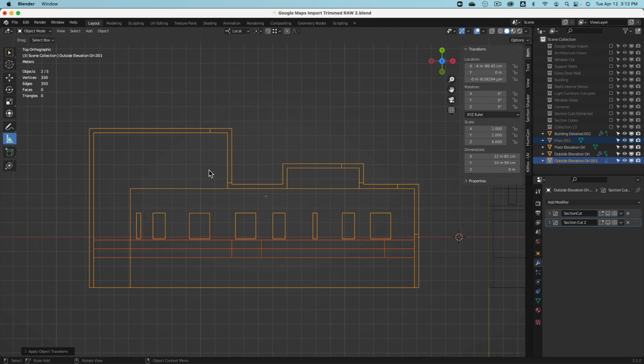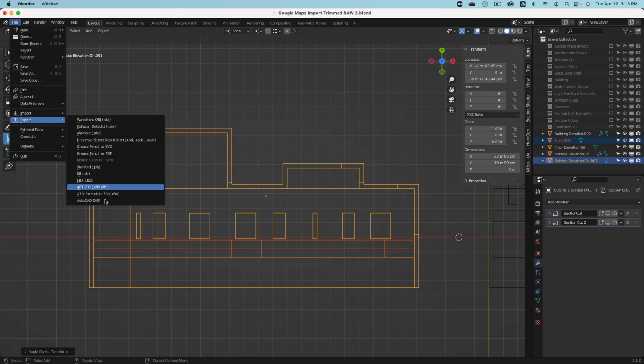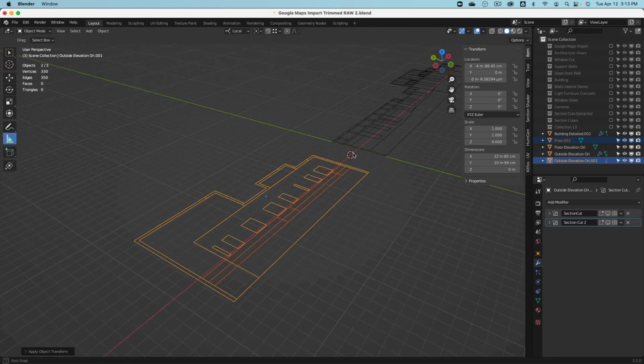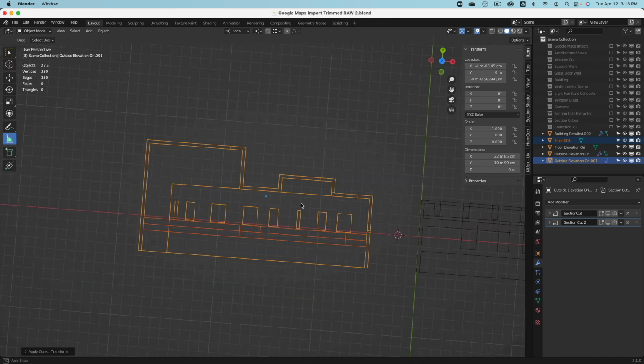In this hopefully really short video, I will show you how we can export what we see here, the linework, into DXF and then send that to Illustrator so we can create interesting renderings of a plan view, section view, or such. This is a section cut through the building, so this would be perfect to bring into Illustrator and then visualize how a lighting plan, for example, could look like as a section and with light counts and all that stuff. Okay, so we will bring this over to AutoCAD. Same process as always. Now you can see everything is put down onto the ground.